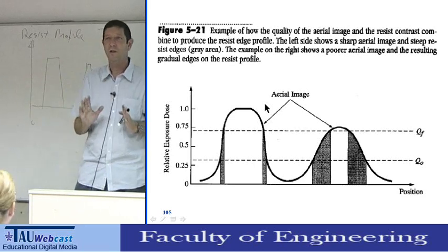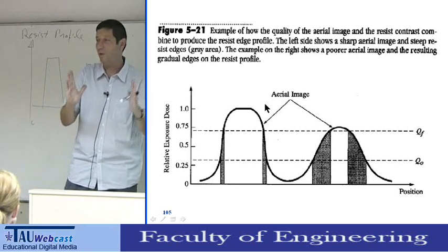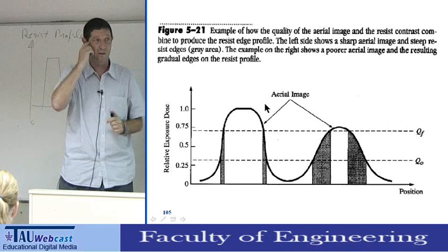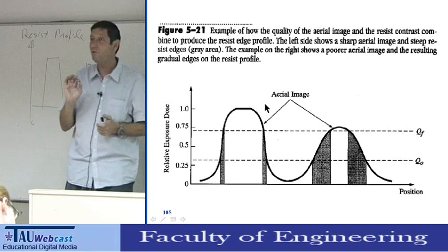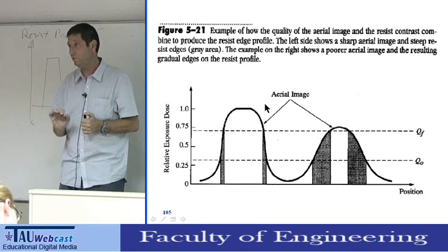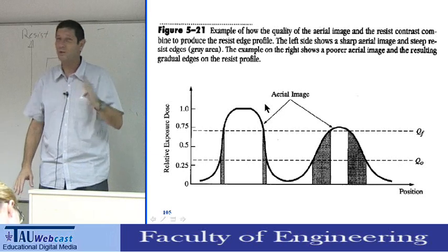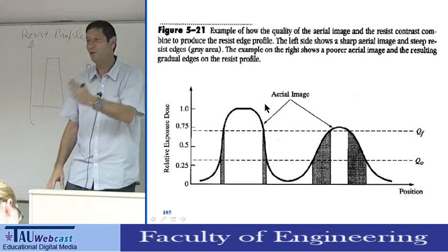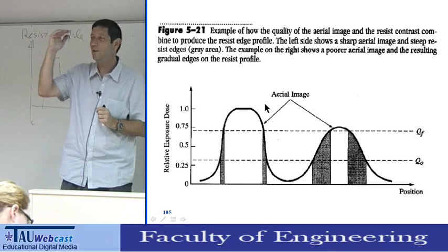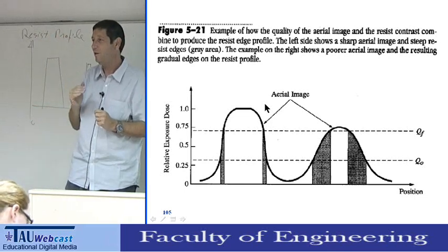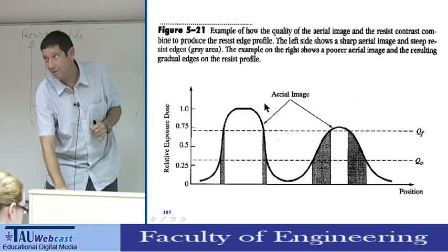It's a good question. Everything I'm telling you now is good within a certain regime of operation. If you take a photoresist and expose it with an intensity which is too high, which is sometimes common if you use laser exposure, then it's a different ballgame. It's a different model. You reach saturation, you depend on the intensity, but it's not good. There is some maximum allowed intensity which people usually use for normal photoresist. But usually it depends on the dose, not on the intensity.